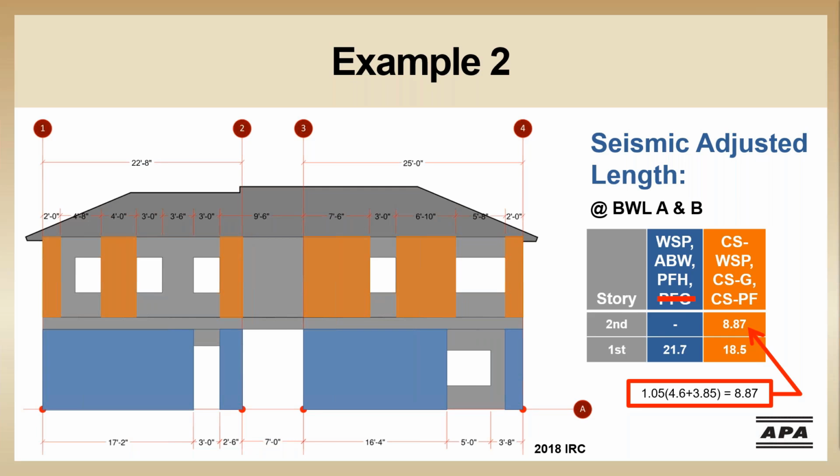Our 7-foot 6-inch wall is just barely within that 20 feet. So we're just barely getting 20 feet in between here. So we do definitely need to keep that 7-foot 6-inch wall. Unfortunately, the 7-foot 6-inch wall isn't within 10 feet of this end. So we do need another wall in between.